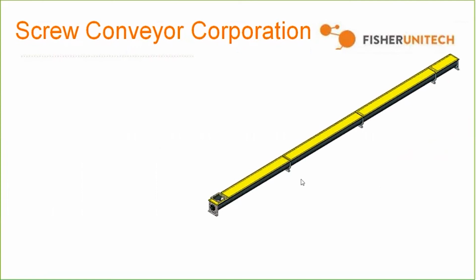So if you were to put in a form that you wanted a screw conveyor that was 600 inches long, depending upon the size of the standard section, you might get 3 or 4 sections depending. So this automatically inputs not only the first section, but it will automatically input and mate the subsequent sections, and then have a custom section on the end and put in all the necessary hardware and other supporting parts in order to create the screw conveyor. And so now they've taken a process that would take a few days and taken it down to just minutes in order to create this via DriveWorks.